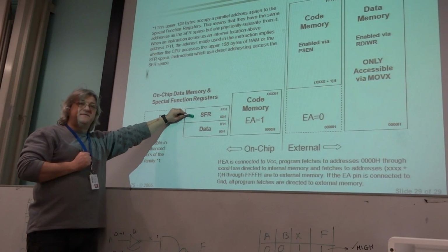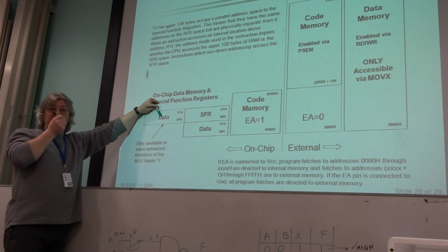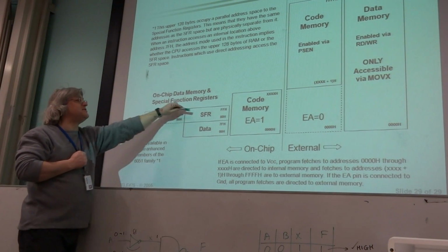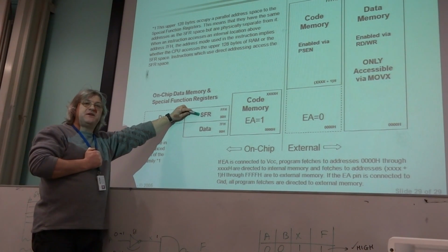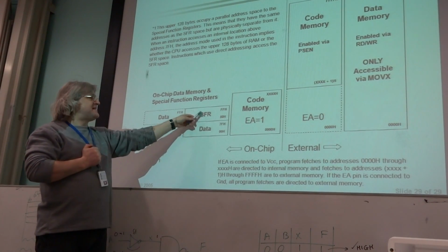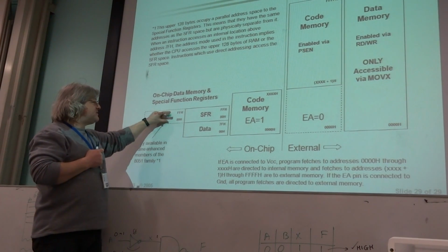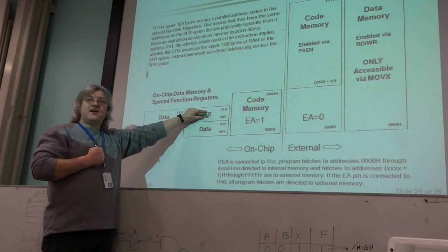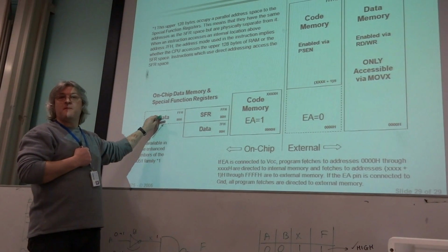If you happen to have an 8052, in parallel with the special function registers, there's another block of data memory that's general purpose. It sits at exactly the same memory locations as the special function registers. And we're able to achieve this because we have instructions that we can use to access these, and a different set of instructions that only work here. So it's implicit in the instruction whether you're trying to talk to this set of memory, or things over here. If you do direct addressing, you always talk to this. If you do indirect addressing, you always talk to this.